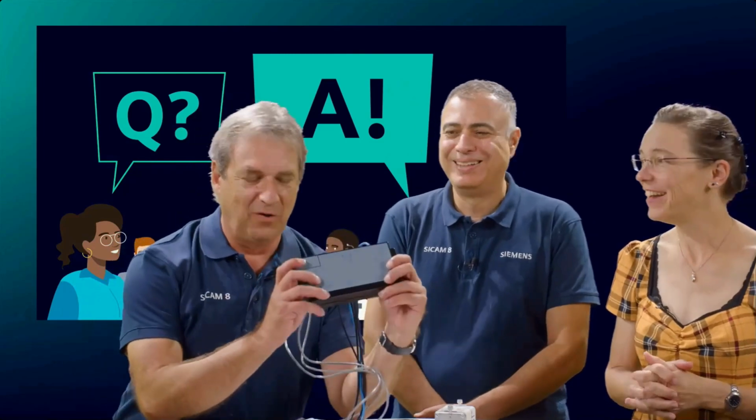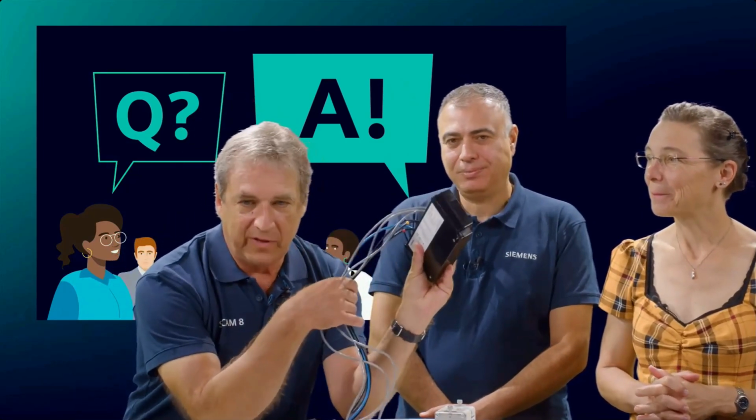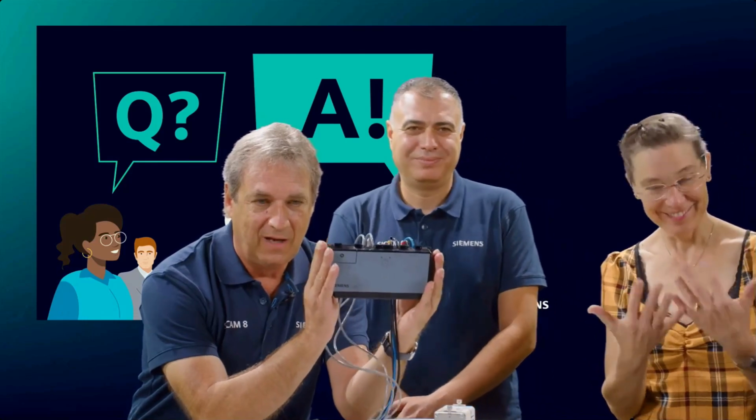Maybe a bit different, right? Okay. So you were talking about milliamperes. There is no milliampere input, but by using these interfaces, there are so many devices that you can connect, for instance, using Modbus RTU, Modbus TCP/IP. So via these interfaces, you can connect them. And the number of analog inputs, this is a full-blown RTU. I repeat it again, I'm pretty sure you will never reach the limit in a substation. Okay, I hope this answer helps you.